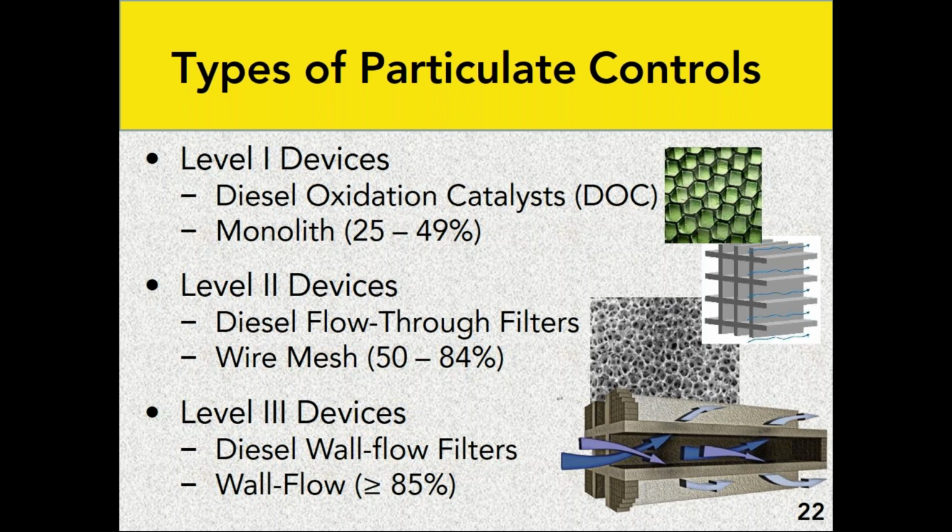You can see a blown up picture of it right there in the middle right hand side. It looks kind of like a sponge. They aerate this stuff as it's cooling so that it has millions upon millions of tiny little channels and holes, which are only big enough to allow exhaust gas to pass through.